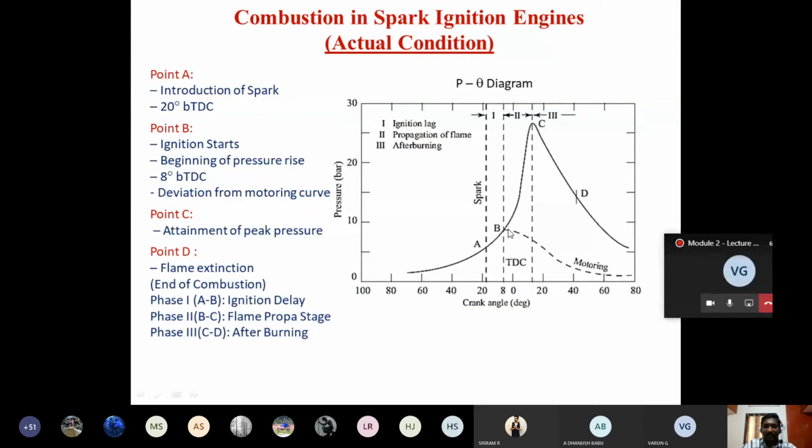Now, normally we used to do this, let us say if you have a diesel power plant, or a huge engine, right? In the case of a diesel power plant or a marine diesel engine, before you start or crank the engine, we used to start the lube oil pump, start the cooling water pump, and then we used to have a motor called the starter motor. That motor will start. The engine is not going to run by itself; that motor will drive the engine.